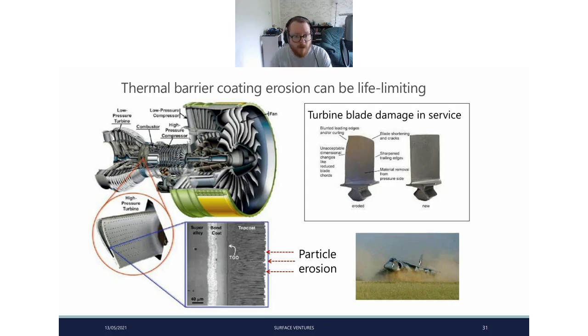So let's look at a bit more of a practical example before we get on to the demo in a moment. We have a thermal barrier coating here on the vanes of this turbine. Typically the structure of this, the actual bulk material, would be a superalloy, generally nickel-based, something like Inconel, various grades of which. There's a thermally grown oxide bond coat, essentially acting as our adhesive layer, and then a top coat produced by PVD. You can see a nice columnar structure there. It's quite typical of PVD coatings.